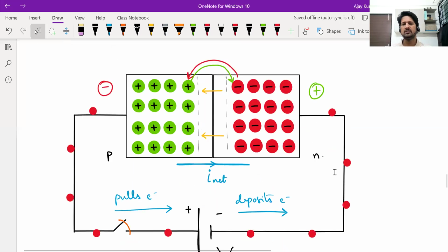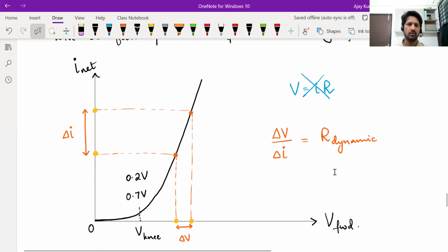So what happens if you increase the forward bias voltage too much? There is a chance that the current increases to such high levels that the material gets damaged, that the semiconductor or the junction gets damaged. So that could happen. Forward bias current is significant, that's fine, but that doesn't mean you can increase it to whatever levels you want, because every material has limits.